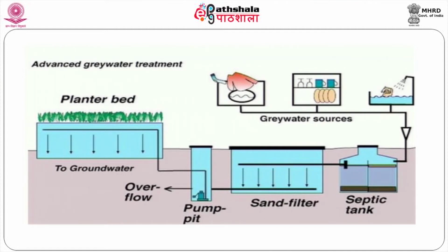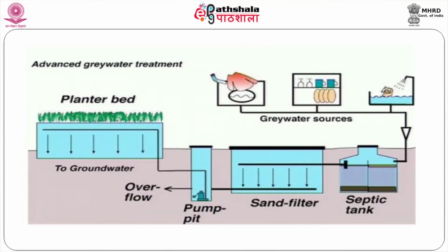In addition to that, if you want, one more reactor as a coarse sand filter in a horizontal or vertical manner, and one more reactor can be a sand filter of fine sand. In this way, we can connect 2 reactors in sequence to remove suspended particles present in the septic tank effluent. The first reactor we may consider as a septic tank or a holding chamber. Some settling will occur here, and some anaerobic activity may be there in our septic tank, followed by filtration in a 2-stage or single stage reactor.